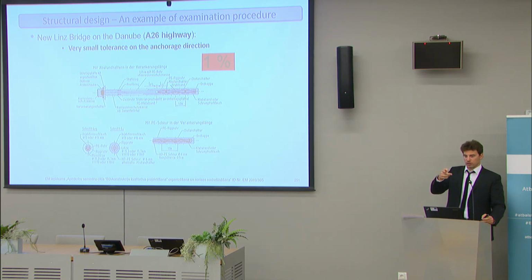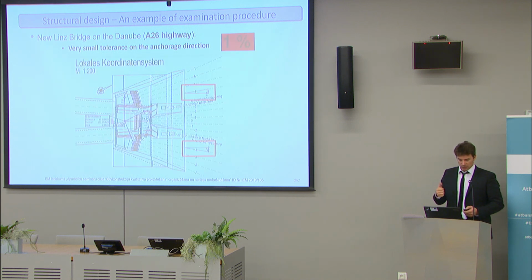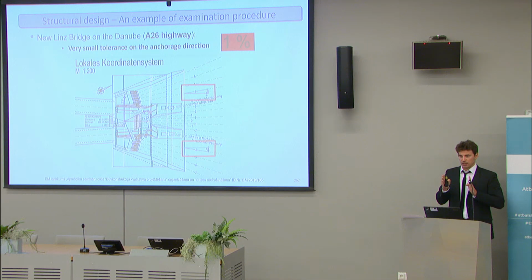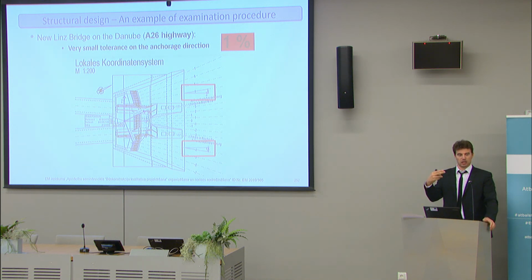So, for example, first of all, the surveyor must come and position your machine so that you start perfectly in the right direction with less than 1 degree tolerance. Then you need a device placed inside the drilling machine that computes where you are. It gives you the position, and with that you can see where you are. If you are inside the tolerance, everything is okay, and you continue to bore that way. Otherwise, you have to put in a bend sub, something that allows you to make a curve, and then you start drilling in another direction, and you change the position, and you follow like that.